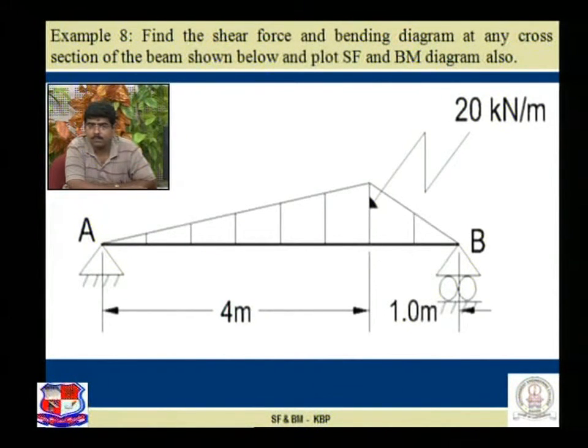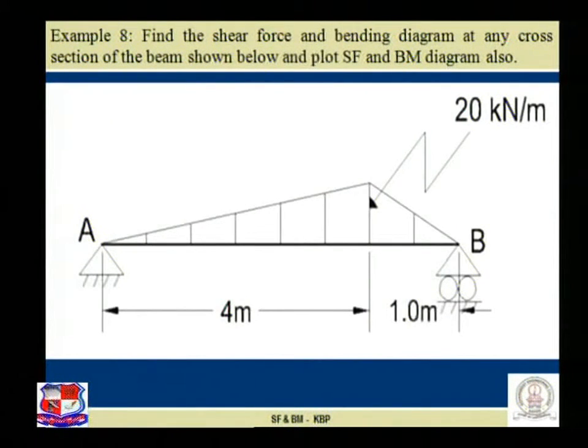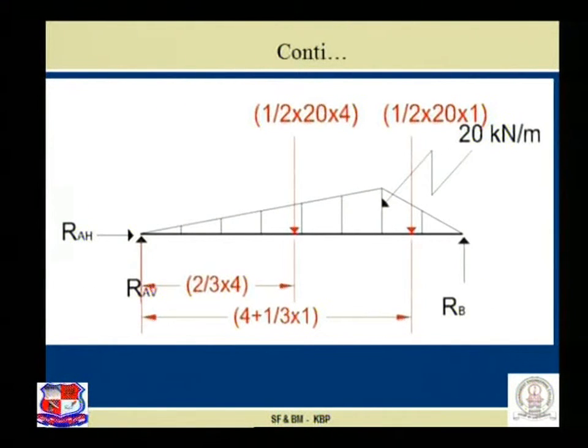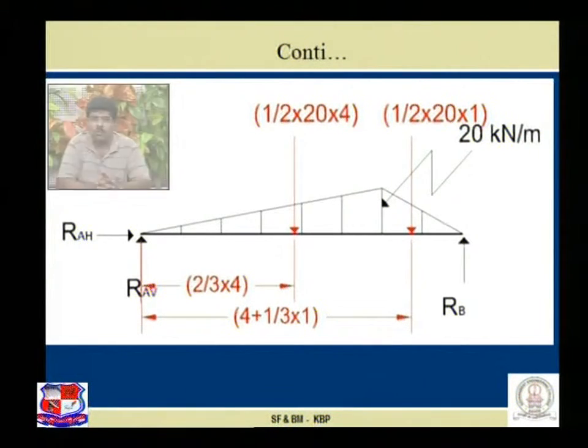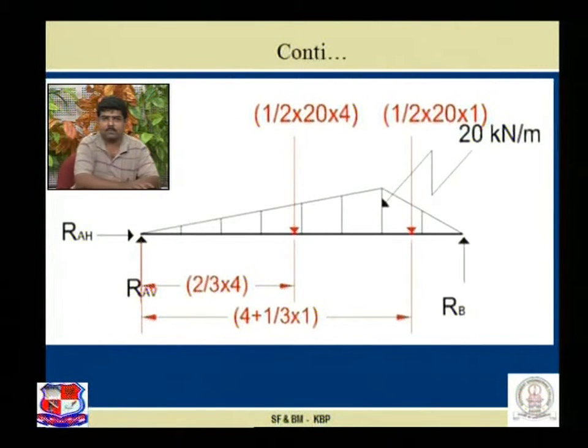As usual, step number 1 for us: calculation of support reaction. Before we proceed to the calculation of the support reaction, it is utmost important to simplify the figure and convert the UVL in terms of equivalent point load. Just see over here,